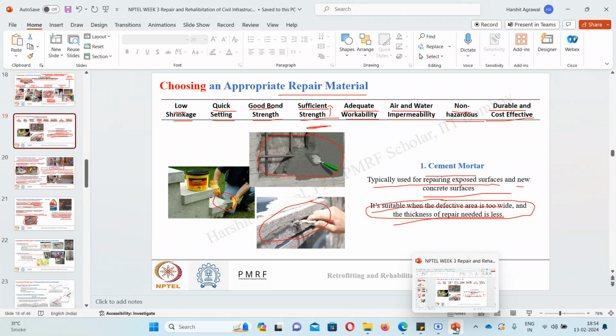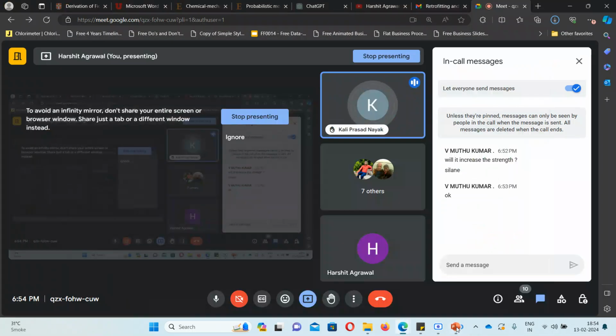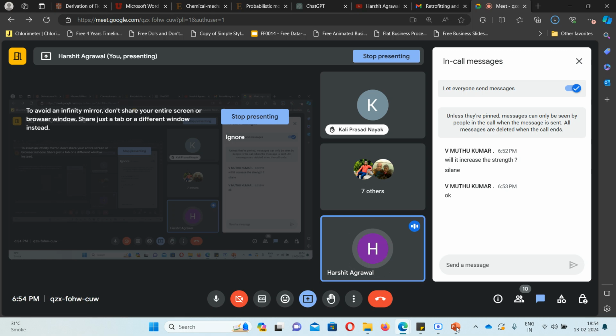So from the bottom, normally in these staircase slabs, nobody takes care of those things. Gradually, because of seepage and leakage, this bottom reinforcement is getting corroded and swelling of concrete happens. So how to address this type of issue? This is a common problem in residential quarters. So what you can do initially, if you see spalling of concrete has occurred, you can use suitable repair material first to regain the shape of the concrete properly and cover the reinforcement again.